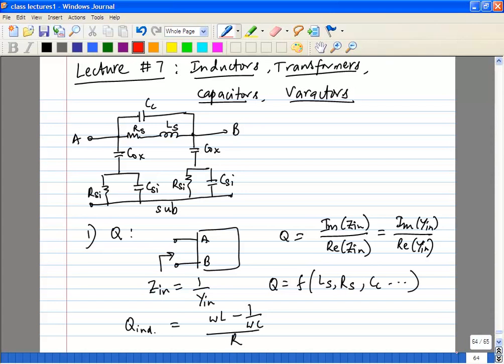So in general, when you want to design your inductor, you want to use a higher metal layer. Typically the highest metal layer you have access to would be the one you would start off with. Then you might end up using the next metal layer. We saw last week there are cases when you want to connect to both the ports, you will always need an underpass. So you may use the next layer for an underpass. Or, if the next layer is also a thick layer with low resistivity, you may use a combination of both the layers to create a very good, very high Q inductor.